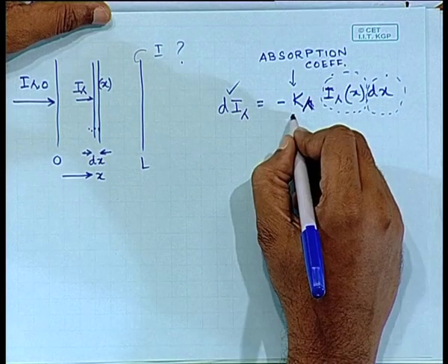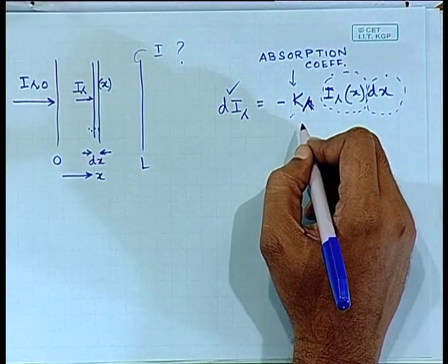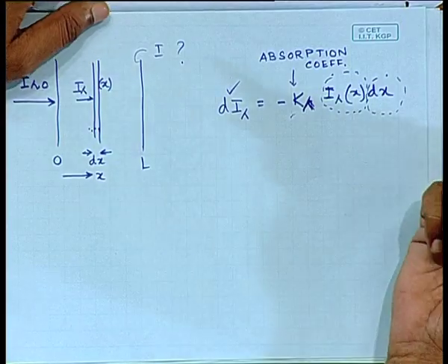No, if you have a gas at one temperature and at another temperature, the energy levels of the molecules are going to be different. So, they can influence the amount of absorption of radiation by that molecule. So, K infinity though is going to be a weak function of temperature. Mostly it depends on the chemical nature of the molecule that we are dealing with. So, this is what is proposed to account for the reduction in intensity.